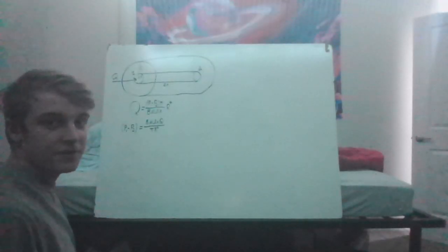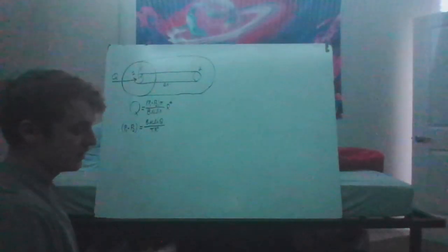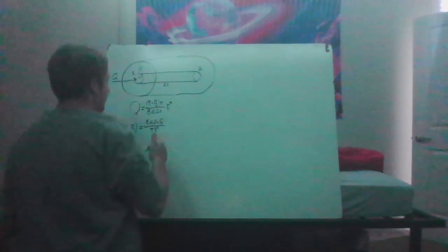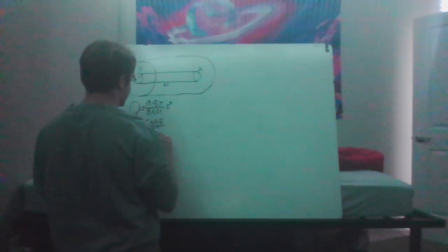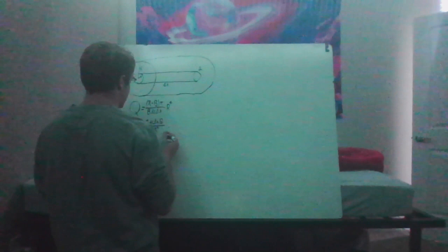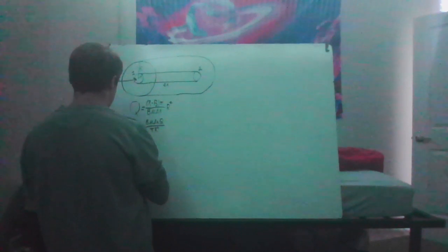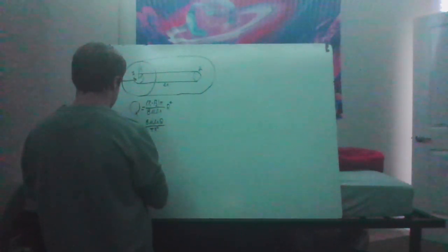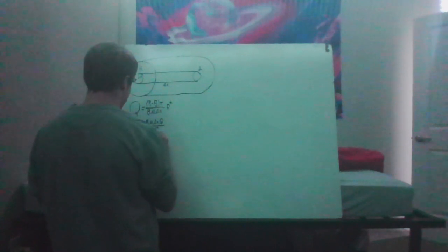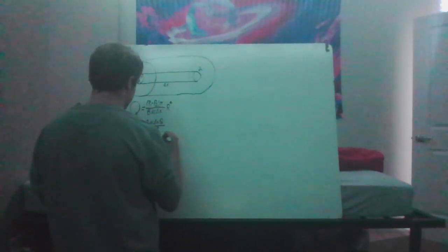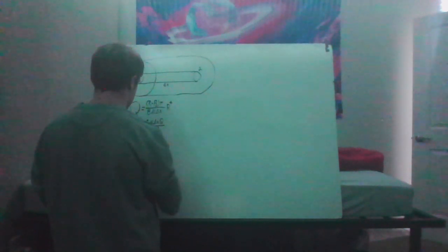And then now, since our frictional heating equation is in terms of the diameter d, we're going to change this R into a diameter. So radius is just 1/2 diameter. So again, P1 minus P2 will be 128 mu delta x Q over d to the 4th pi.